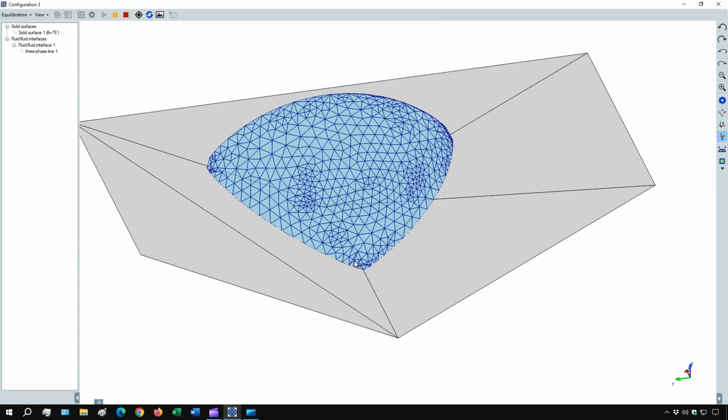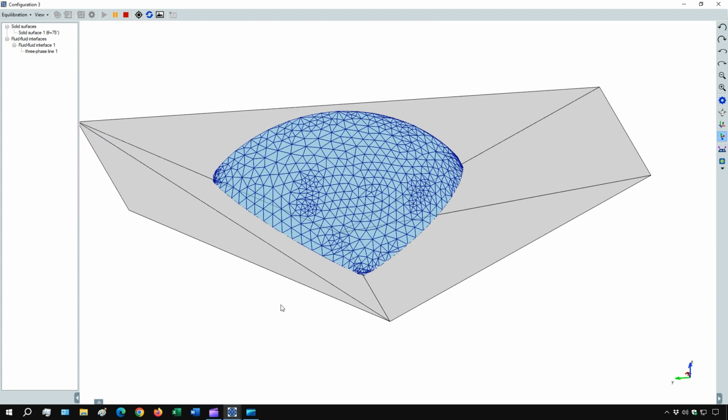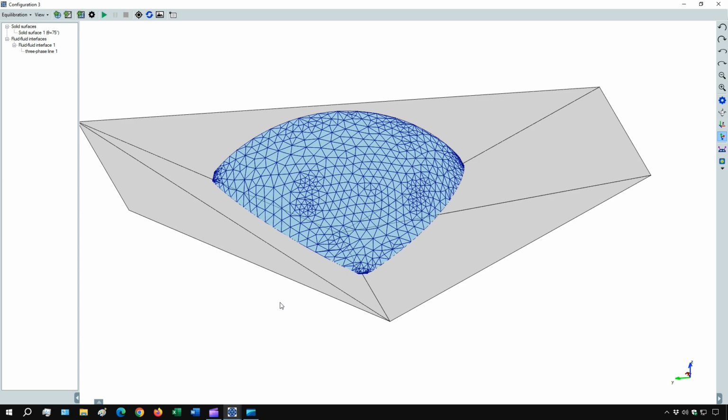Lastly, if you want to save the 3D coordinates of only specific vertexes of a mesh, then you can exploit this tool. First, deselect the Select Only One Vertex option. Then, choose from here the mesh from which you want to select the vertexes, and then select the vertexes for which you want to save the coordinates.